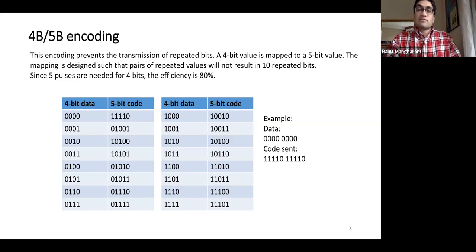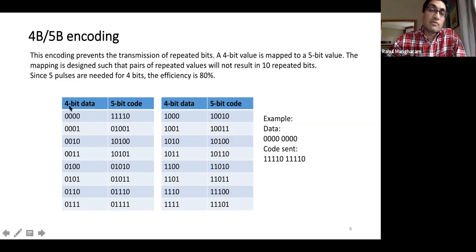The side effect is, okay, I have more bits now. That means my efficiency actually goes down, right? If I encode 4 bits into 5 bits, I only have 4 out of 5 bits that are the actual information, but my whole bit encoding over here is one group, right? It's not just that these 4 zeros became 4 ones. The 4 zeros became this whole thing together. So I have an 80% efficiency in transferring information like that, right? But the data bits have increased over here, right?